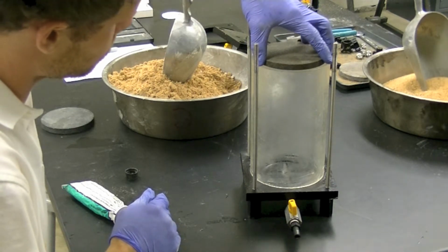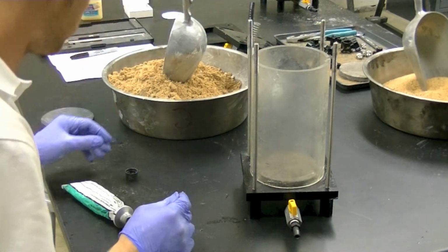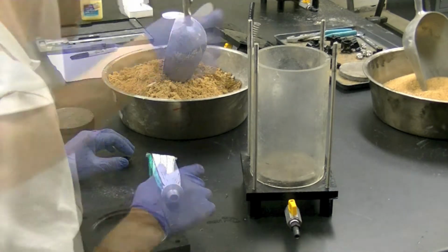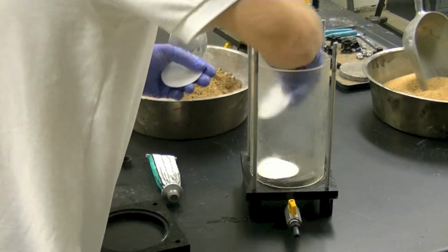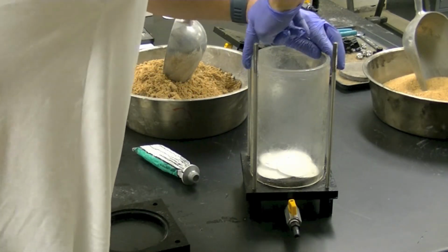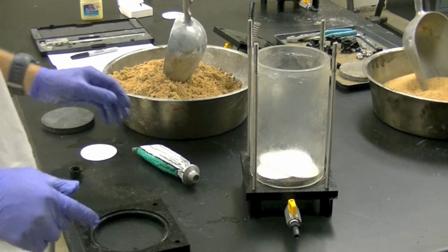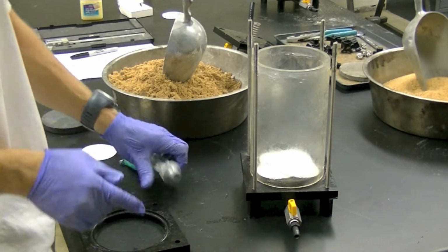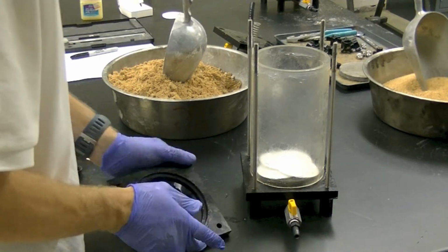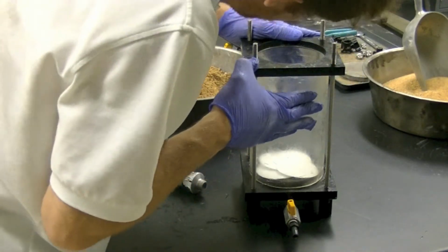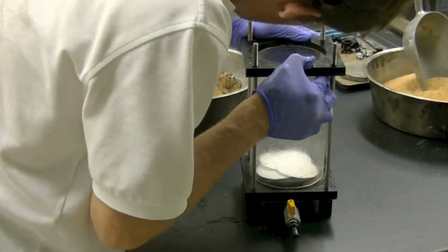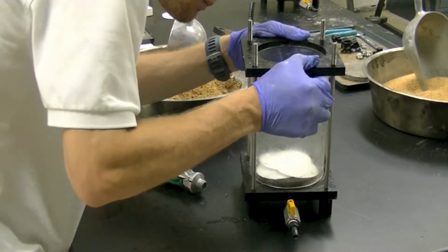Once the tube is on the platen, place the porous stone in the bottom. Filter paper should cover the stone and prevent any soil from contaminating the stone. Grease the outer diameter of the top tube if necessary. Grease the secondary top where the top of the tube will meet the gasket. Ensure the secondary top gasket has seated itself against the outer diameter of the tube. Apply another thin layer of grease if necessary.